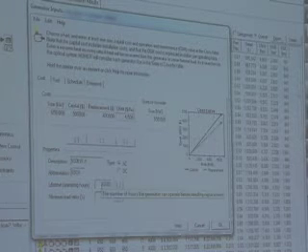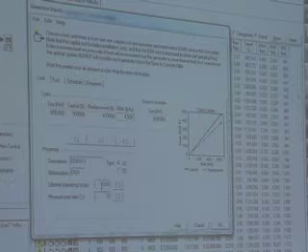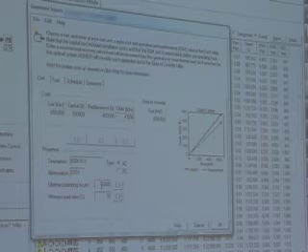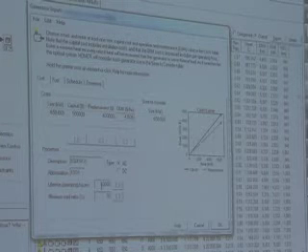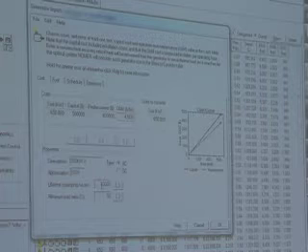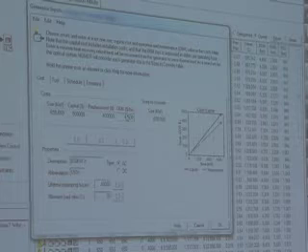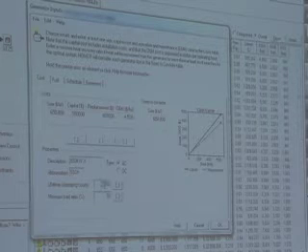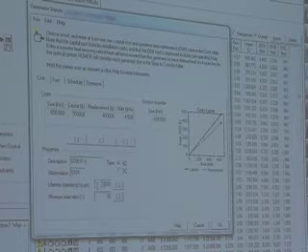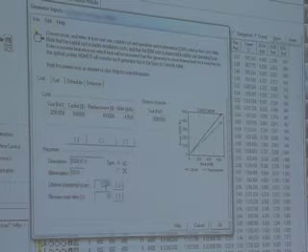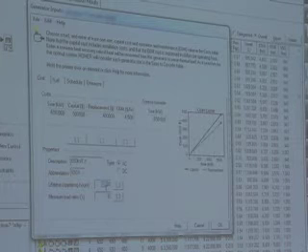Well, that's fine for small generators, but for large generators, instead of throwing it away at the end of X number of hours, you overhaul it. And you can overhaul it over and over and over again. And so there's two ways to handle that. You can either take that overhaul cost, divide it by the overhaul interval, and add that in here to the O&M costs, in which case this lifetime here ends up being, well, how many times can you overhaul it? Then in that case, this should be a pretty big number, because it's not the overhaul interval, it's when you really are done, can't overhaul it anymore.